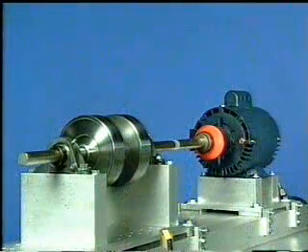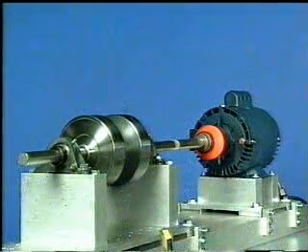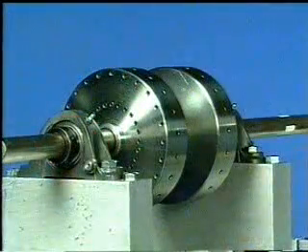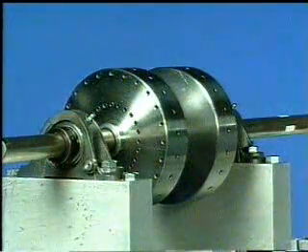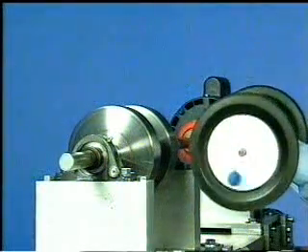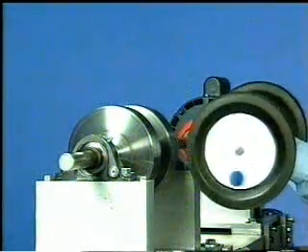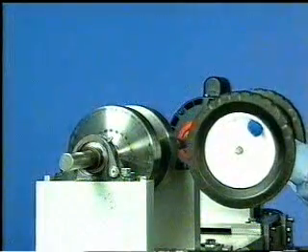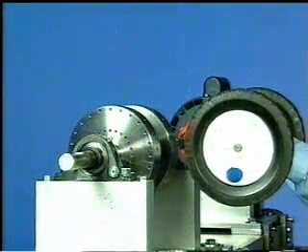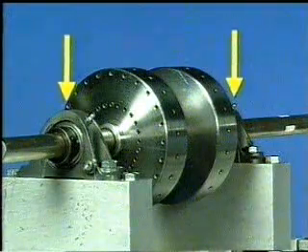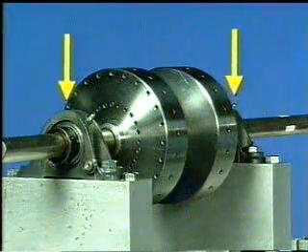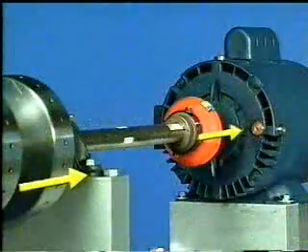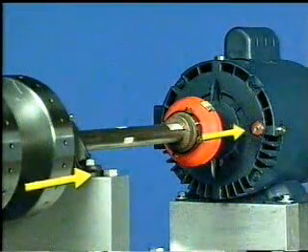When diagnosing an unbalanced condition in a machine, we are usually referring to the unbalance of a component. That is, either the driver, such as a motor, or the driven unit, such as a pump, fan, and so forth. Like the unbalanced wheels that pull on the shaft, unbalance in the machine component pulls the shaft, generating a bump each time the shaft turns. This type of unbalance produces movement in the same direction along the shaft. Therefore, phase readings in the vertical direction from one end of a component to the other will be in phase. The horizontal readings on the component should also be in phase. And axial readings across the coupling should be in phase.